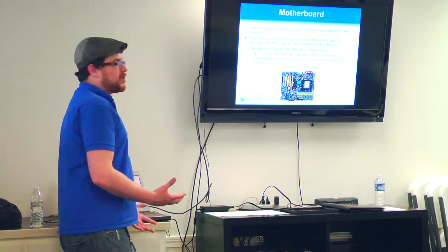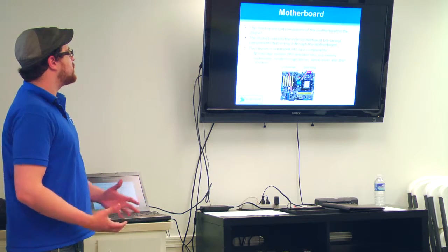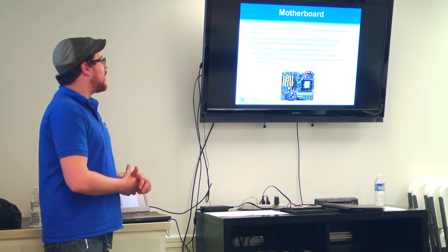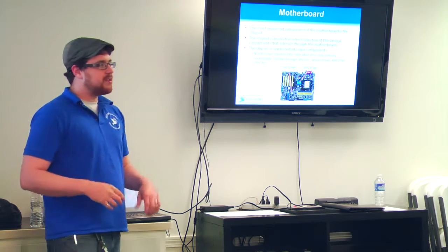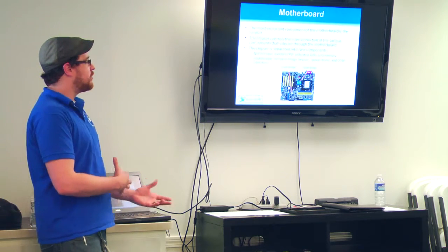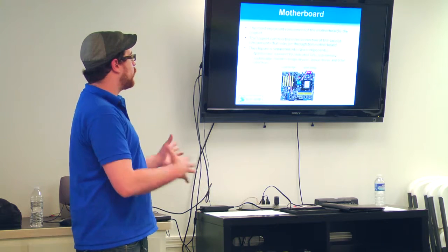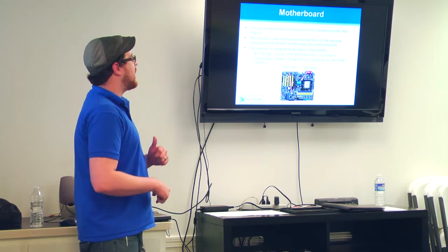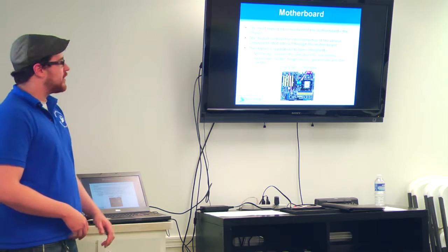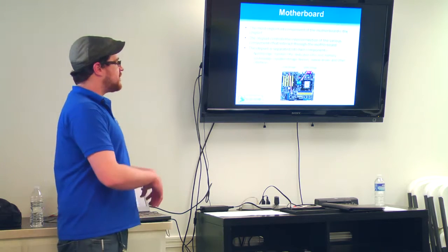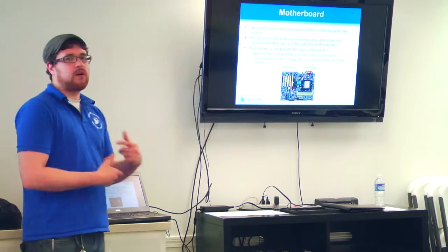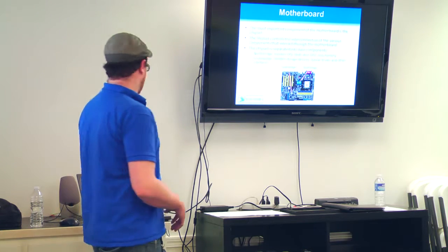The most important part of this is the chipset. You have the Northbridge and Southbridge. This is going to be controlling things like how the CPU operates with all the other equipment, how the GPU works. Sometimes they'll have a dedicated GPU as part of it. That's what I was talking about earlier with an integrated graphics card. But that's controlled all by the Northbridge. The Southbridge part of it handles all the rest of the equipment: storage drives, optical drives, and other interfaces like the network drives. So these aren't the CPU. The CPU does a lot of the actual control of the computer, but this does a lot of the background work, making sure all the parts work together.